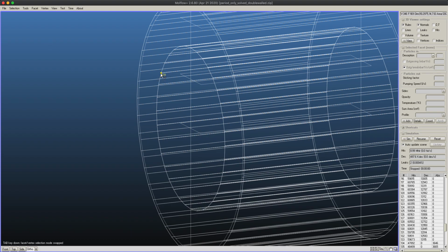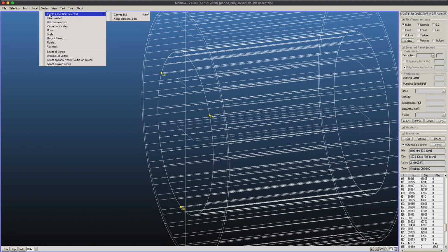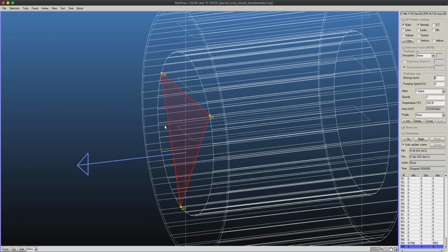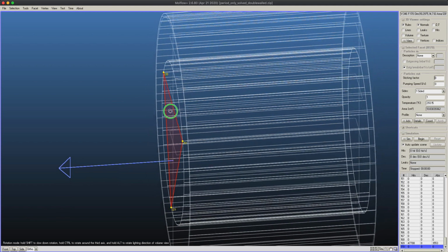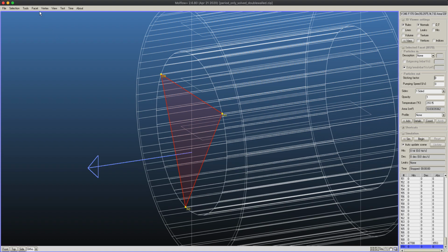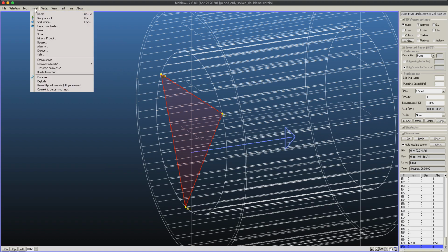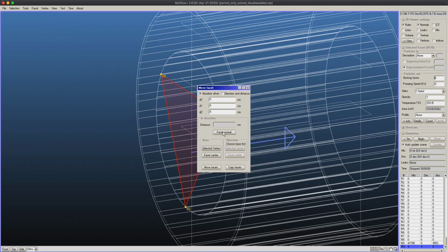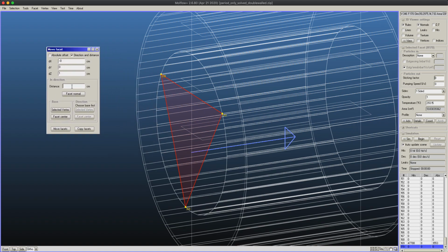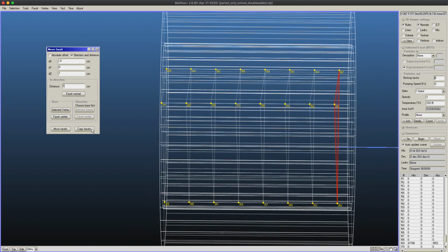So what I need to do is select 3 vertices and create a facet out of them. This is a simple triangle, but it doesn't matter because we will only use it to define a cutting plane. I will just turn it around, and let's say you want to cut it at every 1 centimeter. So I will use the move command. I will move towards the normal vector, and the direction should be 1 centimeter. Don't forget to click on copy facet instead of move facet, and then I can define my cutting planes. All right. So how do I do the actual cuts?